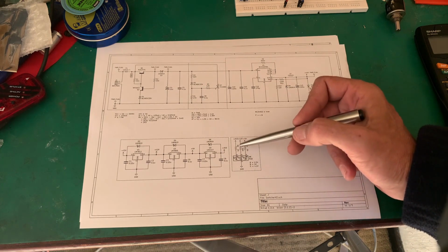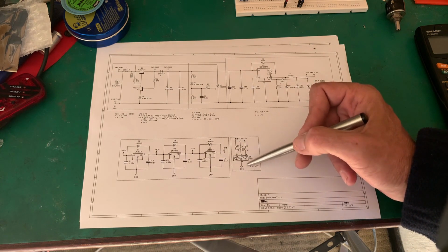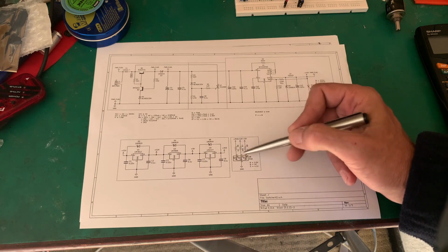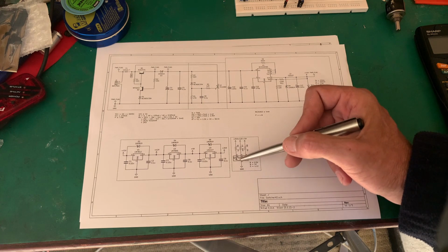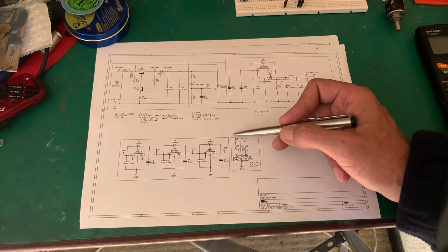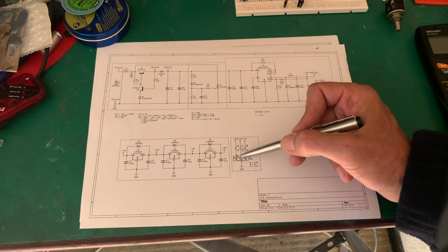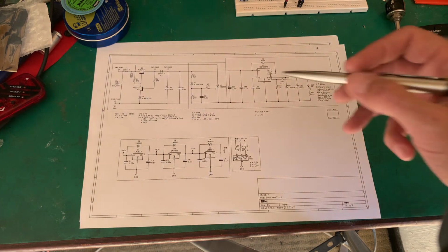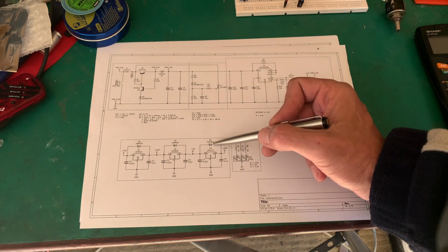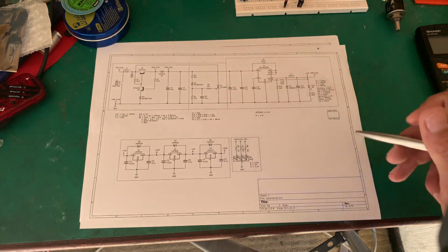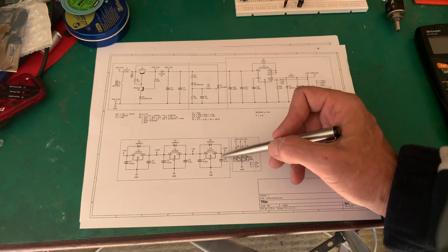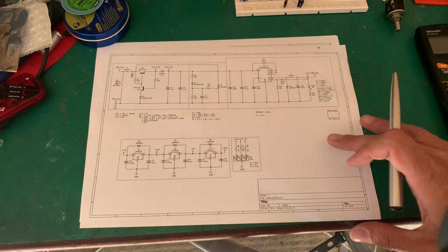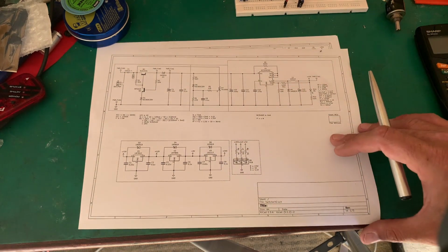And here I was just thinking of using an RGB LED, tying the 3 rails through it. If all rails are there, then obviously the LED will be white, but if you have a problem with whatever rail, then it'll be red or green or off. That's not important. Over the regulators, we've got these protection diodes because of that capacitance, and also if that voltage goes too high. That's where we are to date.